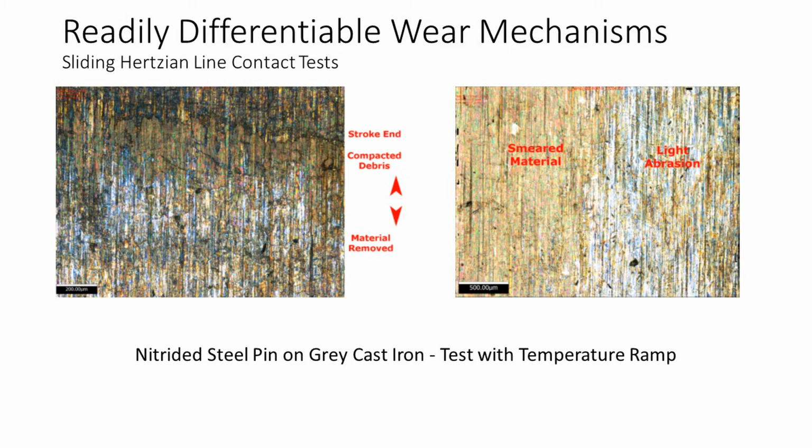This allows good differentiation between wear patterns at different stroke positions. The first test sequence involved a simple temperature ramp, the nominal aim of which was to precipitate scuffing failure. The second test was run at steady set point temperature, but followed a stop-start sequence.